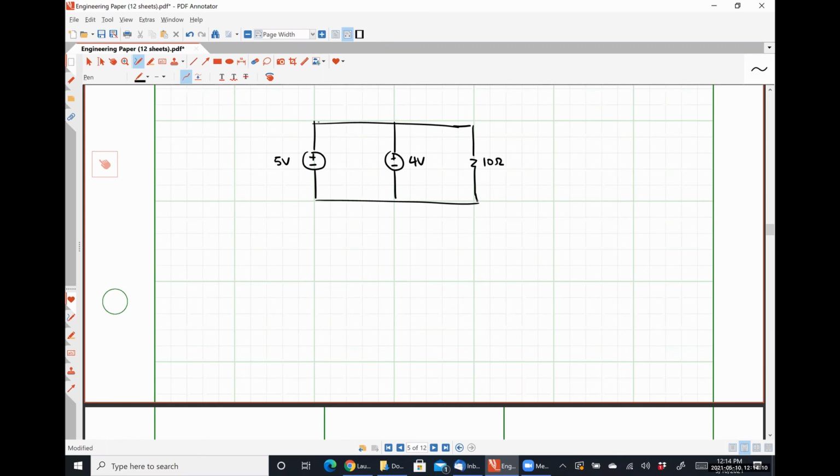So this is why way back in Engineering 120, Dr. Corbett or whoever your teacher was harped on you to constantly make sure the batteries were taken out of your battery box until you had it soldered to the barrel jack. Because if you didn't, you would be putting that 9 volts in parallel with 0 volts, or a short circuit, and you would just drain your batteries and melt everything. This is that, but a little bit more formally.